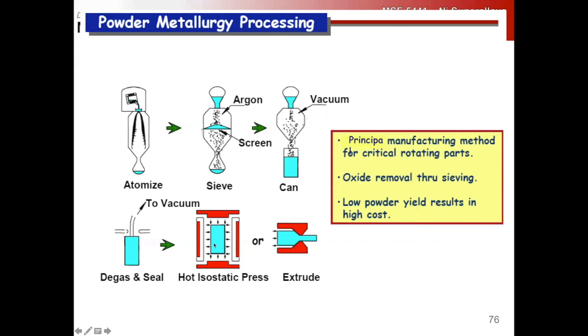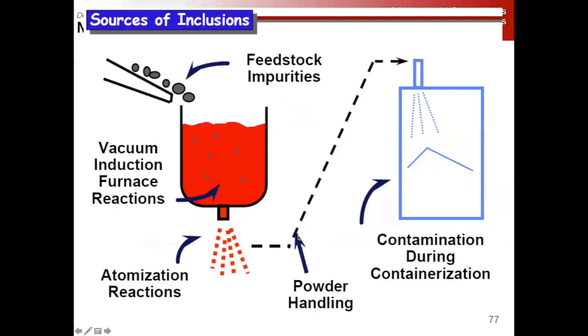You can think of sintering as the opposite of creep, right? The opposite of diffusion creep, right? We're consolidating particles rather than, in creep, moving the center of particles apart. Same physical mechanism, just going in opposite directions, right? This extrusion process is not really used much anymore for production. It is used a lot for fabricating samples, right?